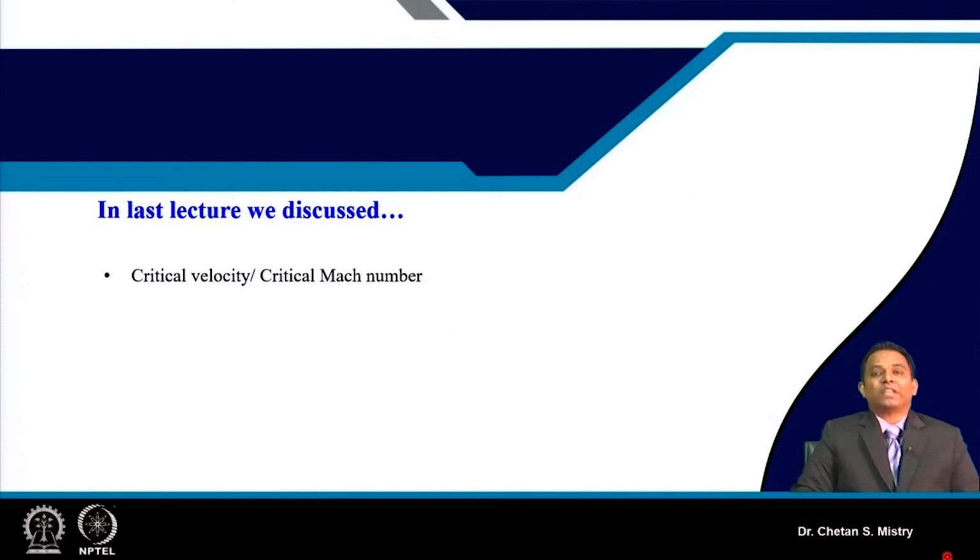Yesterday we were also discussing two different design approaches. First, what we call a sizing problem, and second, what we have defined as a rating problem. Sizing means we are talking about a new design of an engine or a new design of a compressor stage for an industrial application. Under that condition, we know our input parameters, we know what pressure rise we are expecting, we can calculate the rotational speed, and all those parameters are known to us.